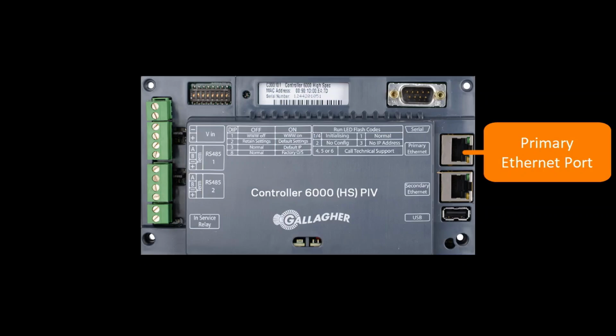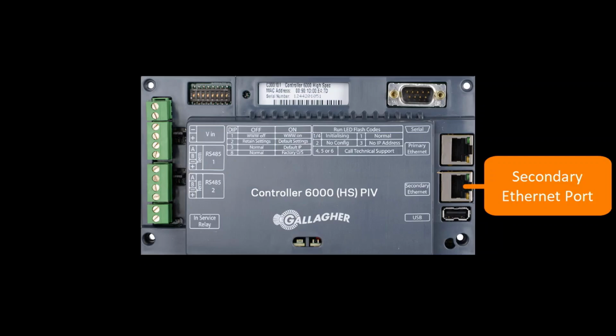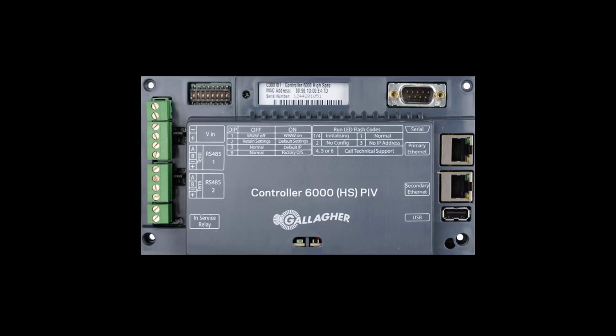The 6000 high-spec controller has two 1000 base T Ethernet ports, whilst the standard 6000 controller has one 100 base T Ethernet port. A secondary Ethernet port is available only on the 6000 high-spec controller. This provides a configurable option for the network to switch to a secondary Ethernet link on failure of the primary Ethernet link. This secondary Ethernet port is provided for redundancy.